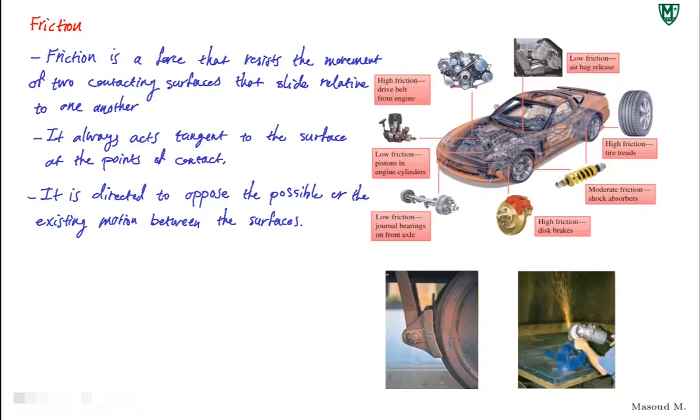Once we do that, we are able to actually draw a free body diagram now with 5 forces: the 4 forces we know from before, plus friction. And then analyze the systems where the friction is not negligible, and we have to take friction into account for those systems, definitely, to get the correct